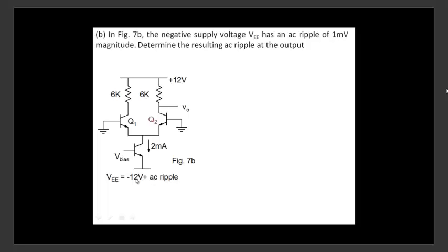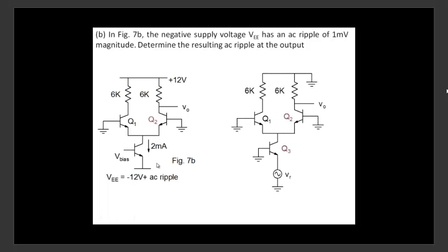And so what you'll find is, as this ripple propagates here, its value will actually get attenuated, because it's common mode. Common mode signals are generally rejected. Differential mode signals are amplified here. All right. So this is a common mode signal here. So let's do that. I'm assuming bias point analysis. We have given 2 milliamperes here, so I know a milliampere here. Bias point is straightforward.